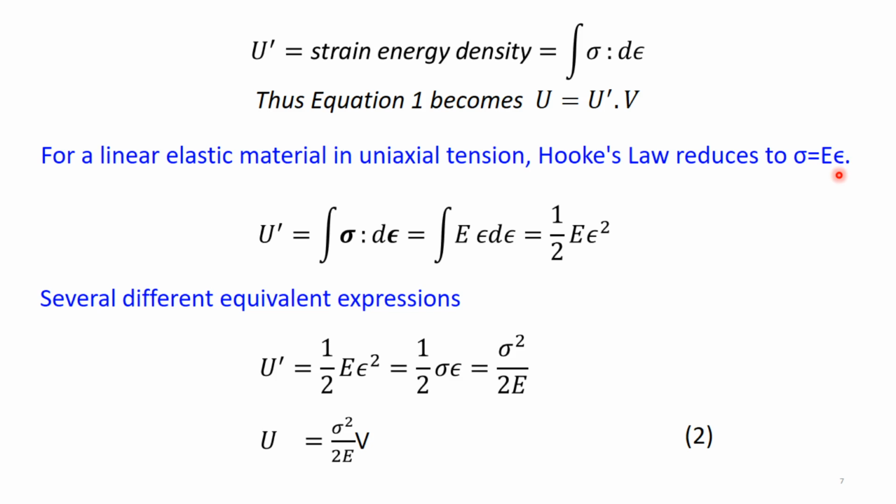This is a very fundamental law which states that stress is proportional to strain, and when we replace proportionality with equality, we introduce a constant, and that constant is the modulus of elasticity. So this is Hooke's law, sigma equal to E into epsilon.